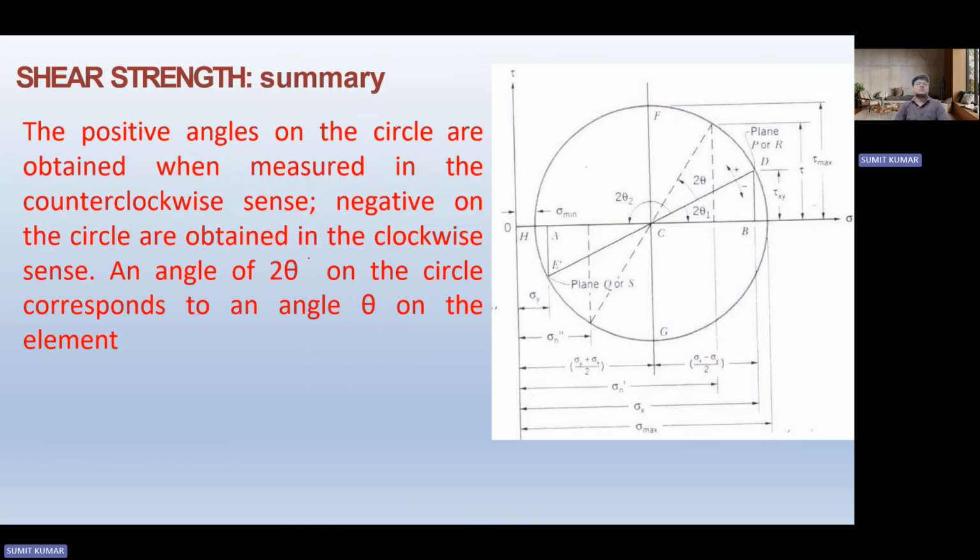Following that, we have understood the shear strength concept, in which we have understood different tests like the triaxial test, direct shear test, vane shear test, and many more things. Afterwards, we have also come across the application of these tests, how this application could be followed, and then the Mohr circle understanding is developed, in which we have understood that twice the angle is made in the Mohr circle, as found in general scenarios.